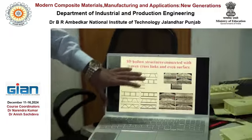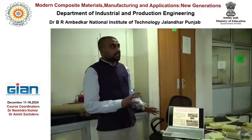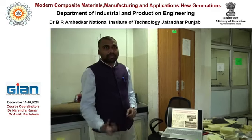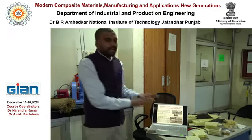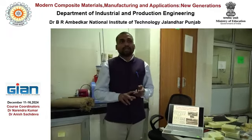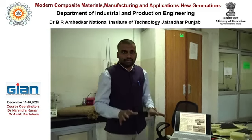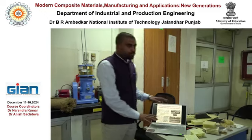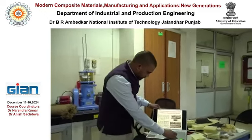And what is the advantage of this integrally woven structure? Again, the load transfer will be more efficient. So there will be no delamination. And to produce this structure, you need a strong knowledge of the weaving technology, of fabric manufacturing technology. And these structures are also produced by nobody in India, right?